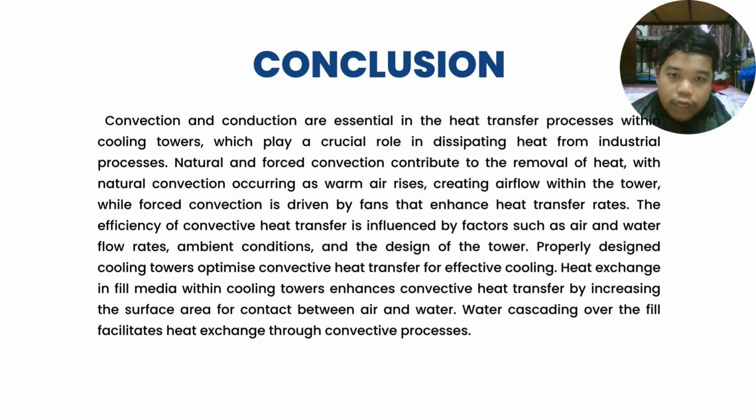Convection and conduction are essential in the heat transfer process within cooling towers. They play a crucial role in dissipating heat from industrial processes. Natural and forced convection contribute to the removal of heat, with natural convection occurring as warm air rises, creating airflow within the tower, while forced convection is driven by fans that enhance heat transfer rates.